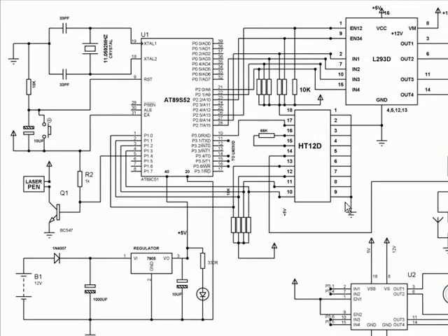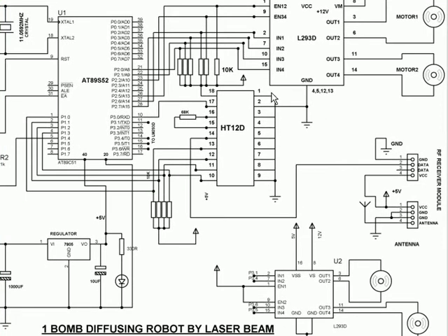These are addressable pins which we are not using, and they are all grounded. Addressable pin meaning we can even change the address of these, which we can separately learn sometime, so that different units can be used at the same place without any conflicting activity on one upon the other. That means if this has a different address, the transmitter will be sending in the same address, so that any other device is not responding based on the transmitter data.